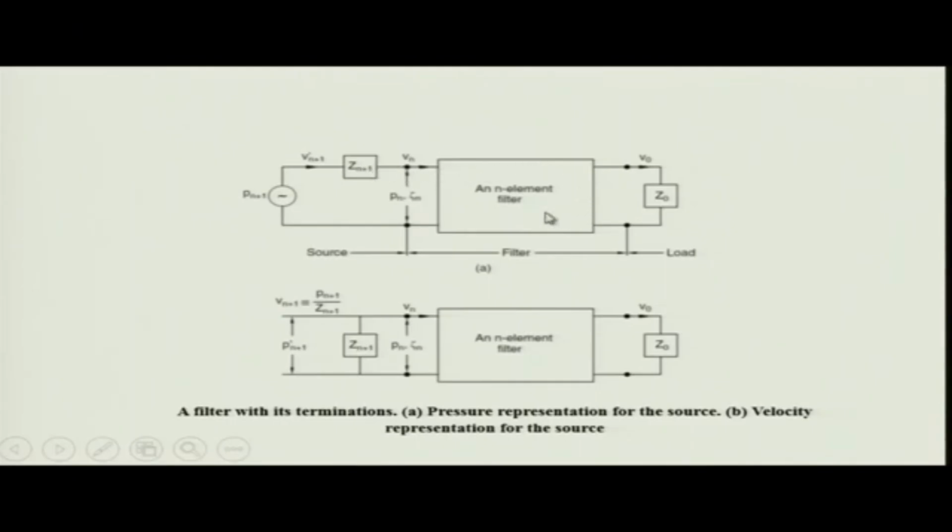If there is impedance matching, all the acoustic power will go downstream and be transmitted into the atmosphere, so the muffler will be useless at that frequency. So the idea of a muffler, at least one of the concepts, is to create maximum impedance mismatch, so that a significant part of the acoustic power for a given frequency range is reflected back, and then you complete the circuit. So this is called the pressure representation of the engine exhaust system.